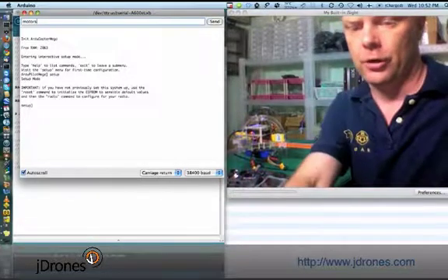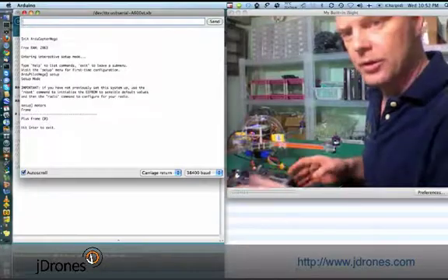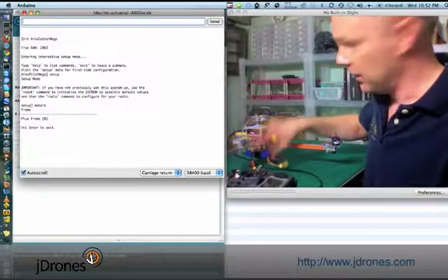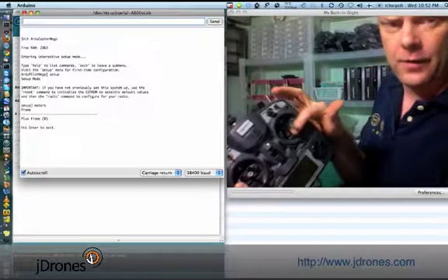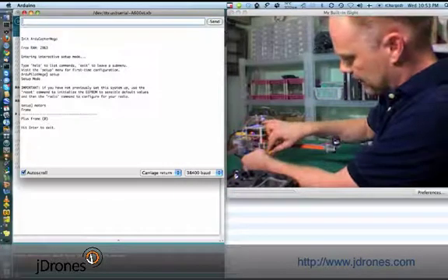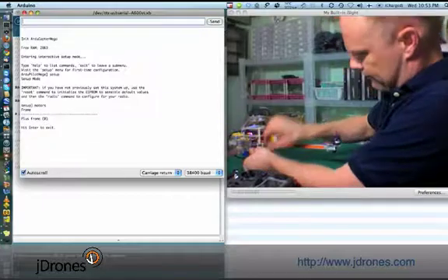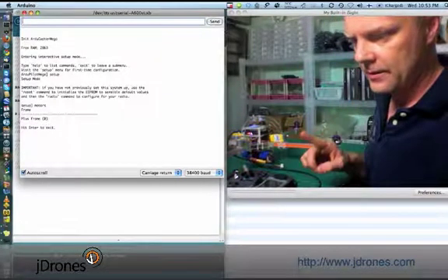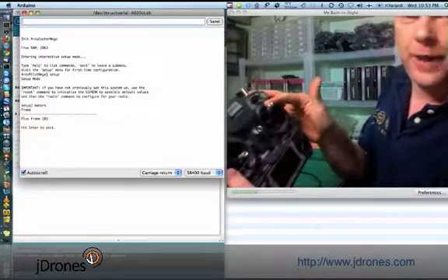So motors. Now we have motors. Basically the motors are armed, but because the battery is not connected, nothing happens. So first of all, full throttle. Connect the battery and listen to the sound the ESCs make. There are two beeps, and now we just go down.